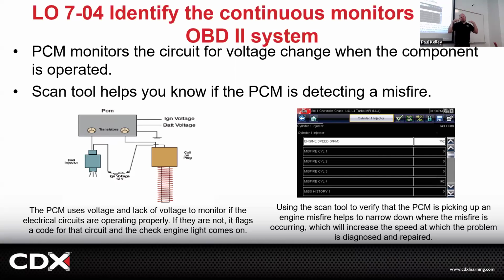Mason's brain sent signals in his nerves to contract muscles and move, right? Well, the PCM does that too. So the PCM is actually going to control this ignition coil. Yeah, like the nervous system. Exactly. So in this injector or in this coil, the PCM can command the injector with 12 volts and ground to spray fuel. Cool. You could do that.